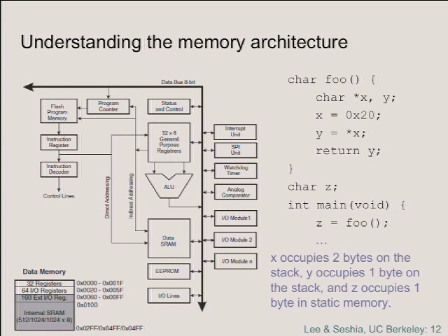Actually, in this architecture, it doesn't. What it means is that the data bus itself is 8 bits, but the address bus is 16 bits. And so the program counter is 16 bits. And so in one cycle, it puts the program counter address onto the bus. And the instruction word size, actually, I think the instruction word size in this architecture is also 16 bits. So the program memory is separate from the data memory. Actually, I'm not totally sure whether that's true in this architecture.